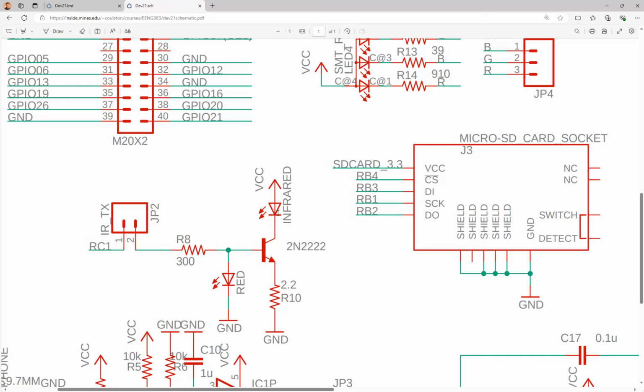Make sense? How come? Because like our other LEDs, we had VCC, and then you want to give it a 1 to turn it off. Yeah, so the voltage drop, it's a channel here. It's like a channel, like a switch. So the transistor is a switch. You give a 1, you turn on this little switch, so it flows current from VCC to ground. Oh, okay, from top to bottom. Yeah, since you already grounded and powered it up here already, it's waiting for this switch. If you turn on the switch, it flows the current. Okay?